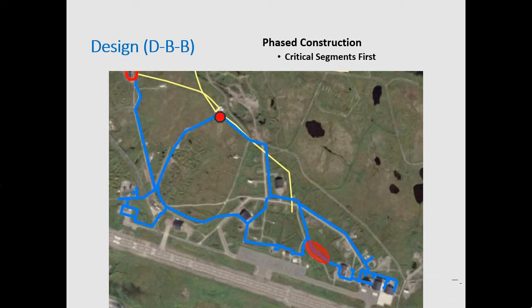So from here, they're putting out 80 PSI. There's a PRV up here. This feeds it. This leg here is a back feed. This segment right here is shut off right now. And these facilities are all being fed through this one pipe that is only providing 20 PSI at a hydrant down here.